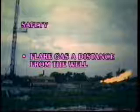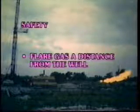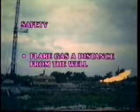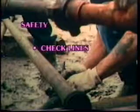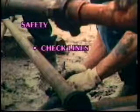Safety enters into all aspects of oil and gas field operations. Gas well testing is no exception. Some elements of safety have already been discussed. H2S is to be flared from a stack or put into a pipeline. Gas is also normally flared unless a critical flow prover is used in a dry gas well. All lines should be pressure tested before the test and properly tied down so they won't move during testing. It is often recommended that a test not be started after dark.